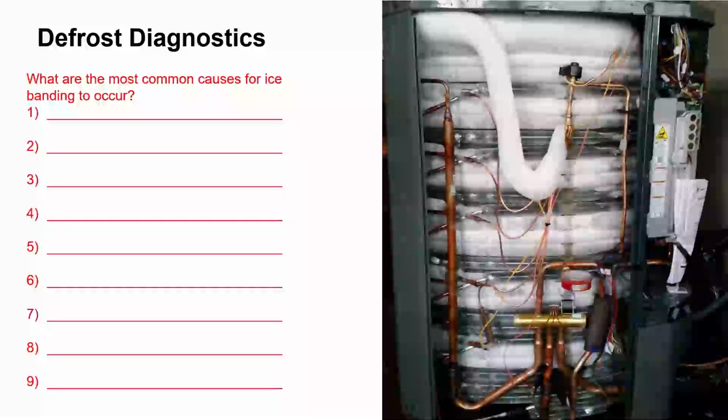We may have to relocate a coil temp sensor to a cooler circuit. Not very common. We've seen it a little bit on the side discharge 15 and the 19, but it's pretty rare. We could have that freezing fog happening in certain areas. Again, if it's just for a day or two, I don't recommend cutting the J2 jumper. It's not worth it.